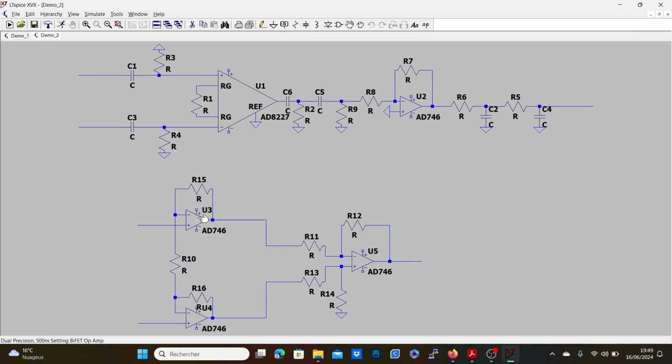You can definitely use, I would recommend precision amplifiers, and by using this, you also have good results. Because instrumentation amplifiers are definitely way more expensive than regular op amps, and it makes sense in a way. So, as I said, here I have a high pass filter just to remove the DC offset. Here is the gain of my amplifier. I have multiple stages of amplification because I've read that, especially for this kind of really sensitive small signals, you don't want to over amplify it right from the beginning. You rather break it down into multiple stages and keep the first stages as small as possible.